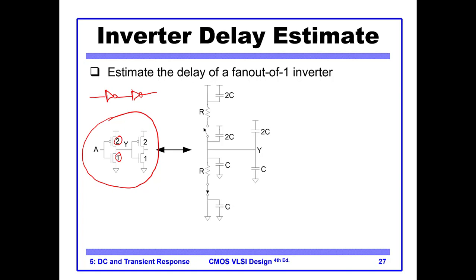If we want to connect PMOS and NMOS in a series connection, and we want the same current to flow, if we want the same current strength from PMOS, we have to increase the width. Remember that ID was directly proportional to the width.